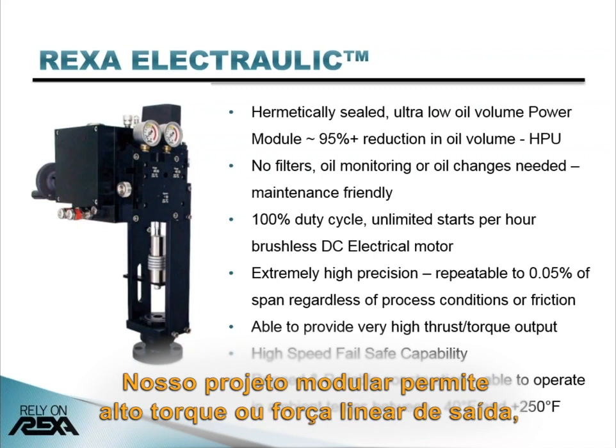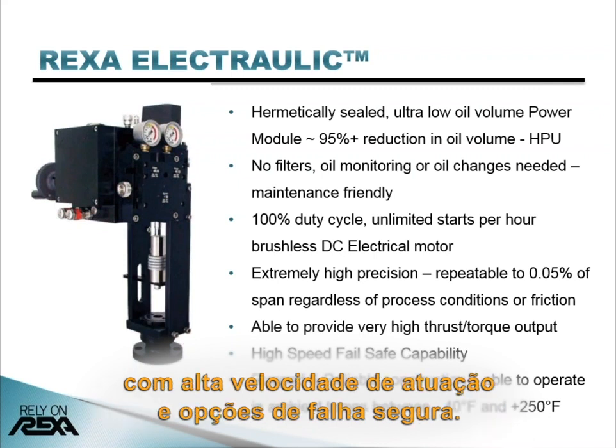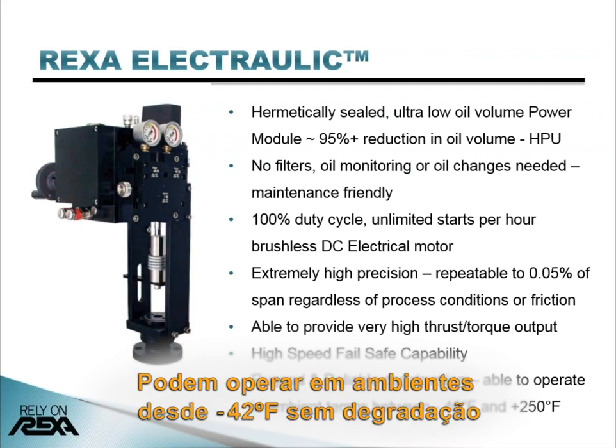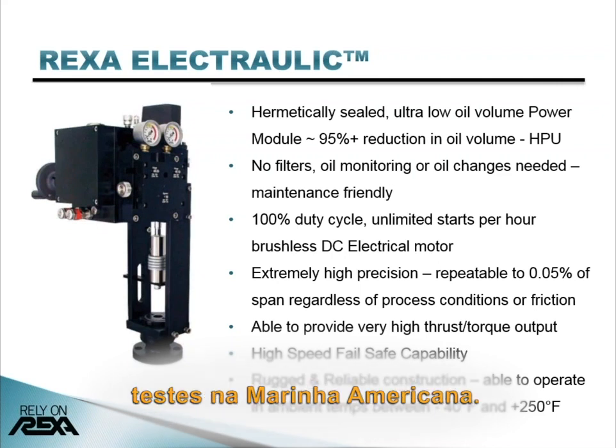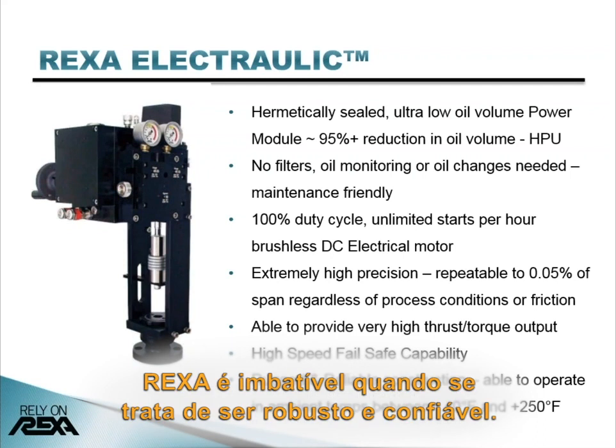Our modular design allows for very high thrust and torque output with high-speed fail-safe options. Operating temperature range is -40 to 250 F without performance degradation. And having passed rigorous testing for the U.S. Navy, REXA actuators are unmatched when it comes to being rugged and reliable.